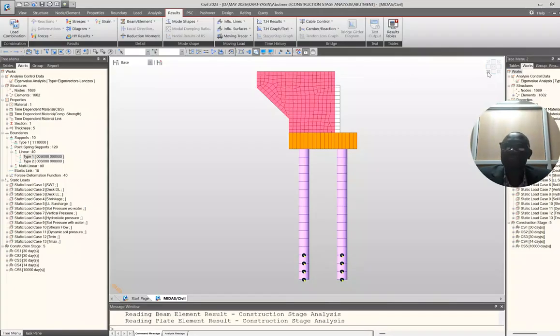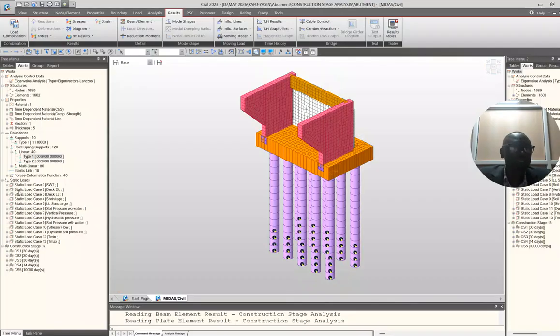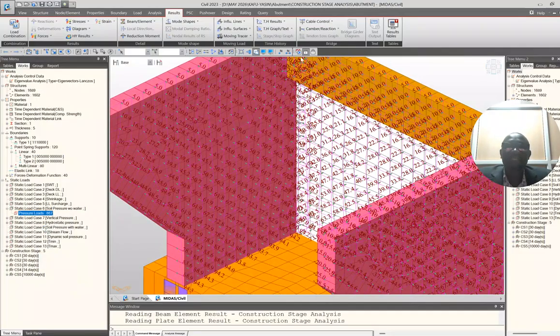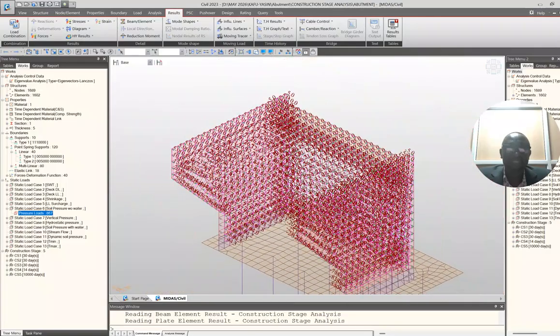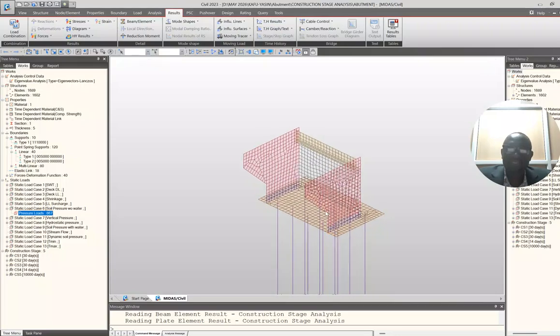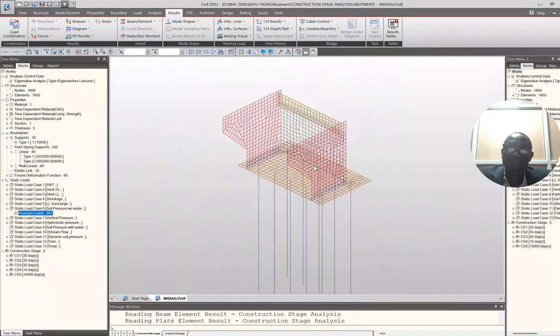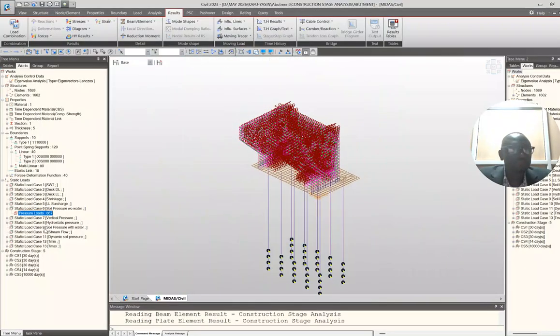While you have loads applied up here, like soil pressure. You see soil pressure is here. You have soil pressure onto this abutment, pushing it along the bridge length and also acting on this wing wall. Even the hydrostatic pressure, and then you come to dynamic pressure